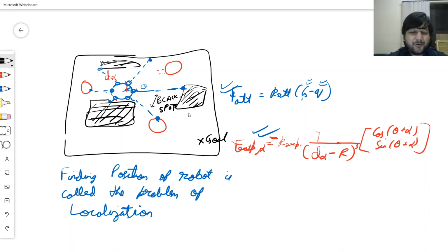So if there's an obstacle over here, it doesn't mean it will collide because of attraction, repulsion, so it will take a little bit of a turn around over here, and only when it comes here, the front sonar will actually look at this obstacle and take a corrective action. But the black spots cause too much trouble. And the only way out is to increase the resolution.